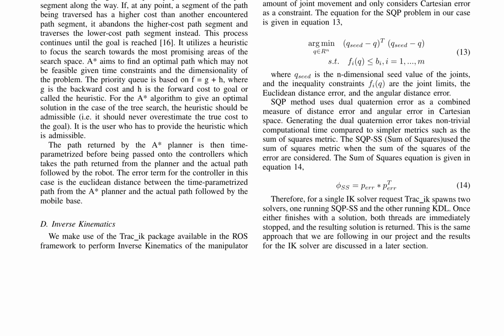Joint position and velocity limits are enforced for all joints, serving as constraints during trajectory planning and inverse kinematic solution finding. The Fetch robot is equipped with various sensors, including a SICK TiM571 scanning rangefinder, a 6-axis inertial measurement unit, IMU, PrimeSense short-range RGBD sensor, and a gripper sensor.